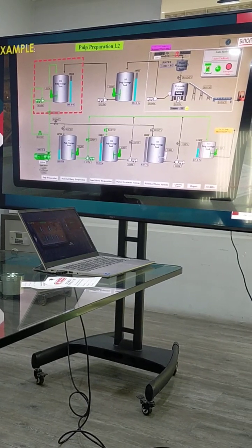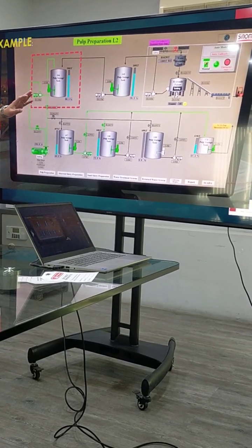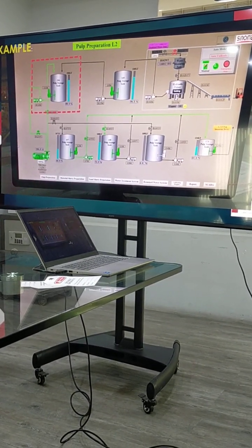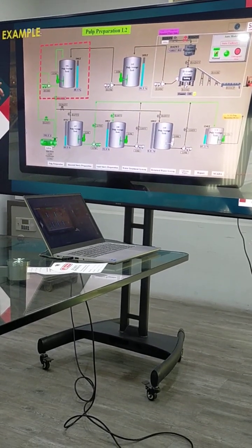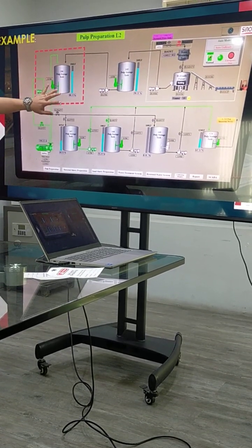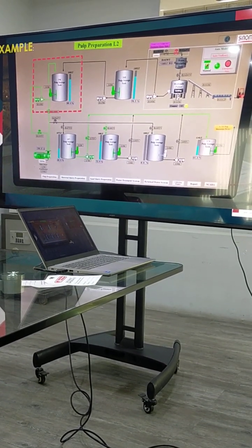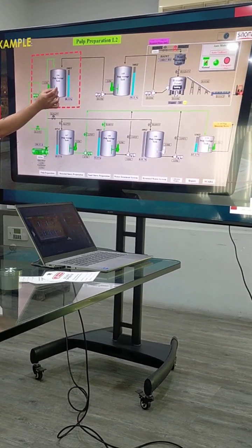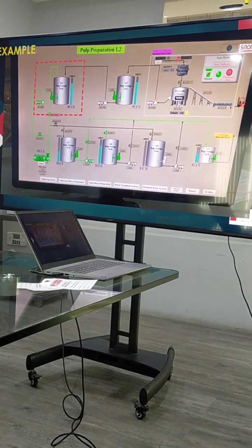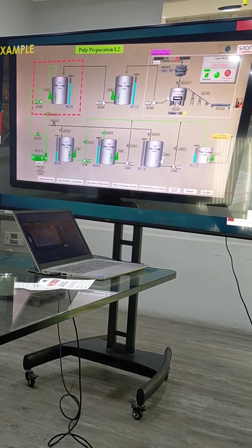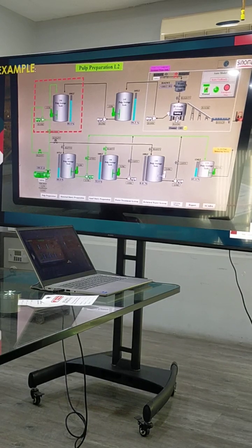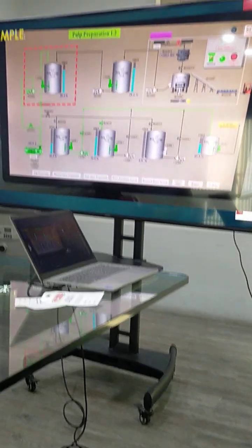If you do not isolate this one, operators can put water, they can transfer water in the control, because they do not know. But if you also isolate all the hazardous energy that will come inside the storage tank, we know 100% that our operators or team members are safe doing their activity inside. So that's the basic principle of lockout tagout. It's not only for the electrical team, but for all employees here. Production and maintenance are responsible for this lockout tagout.